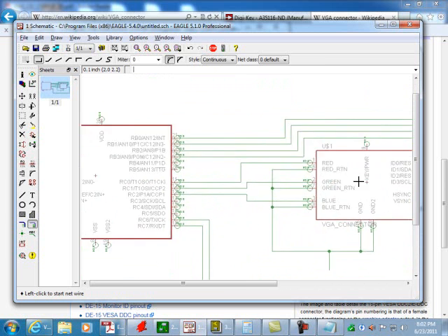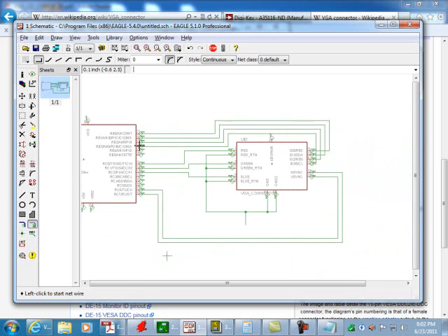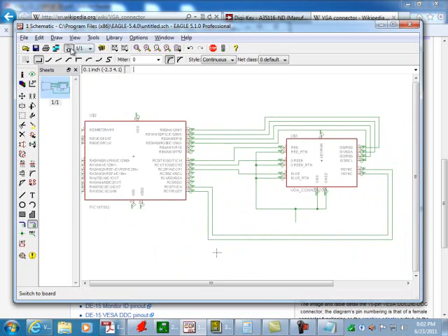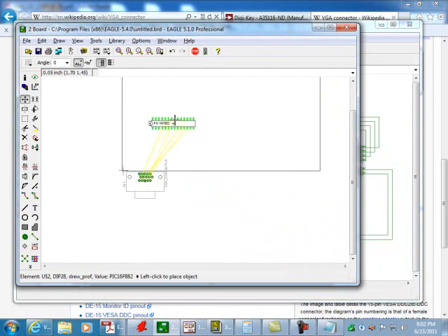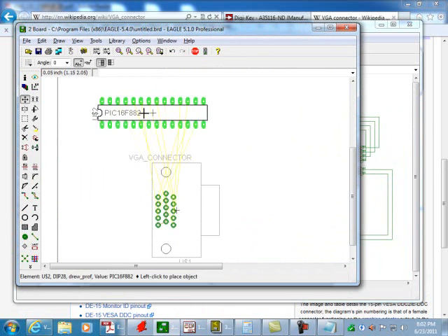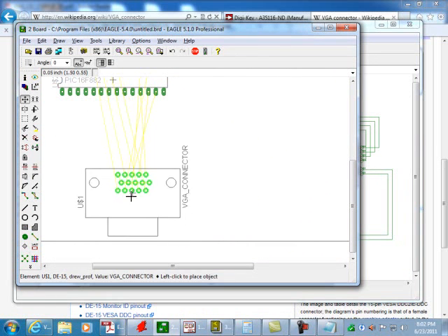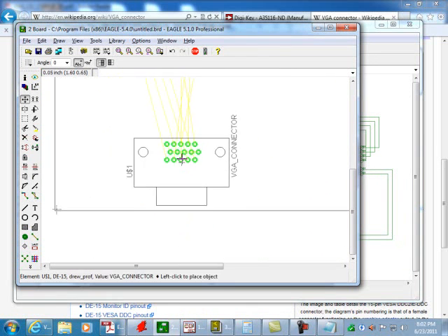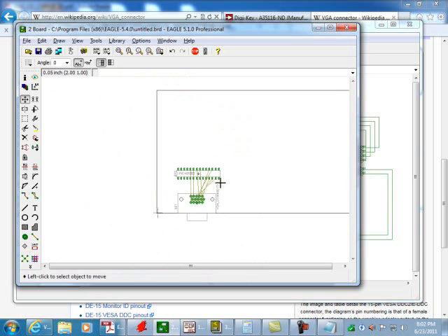So anyway, you can use your actual pin names and your actual pin out names, which is nice for schematic mode. And then when you switch over to your board design, then we have everything already air wired as they should be. And I know that that's my plug because I drew it in there. So we'll put that right down to the PCB edge. Stick our chip there.